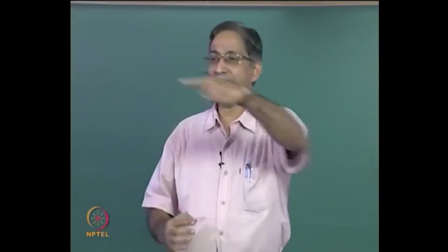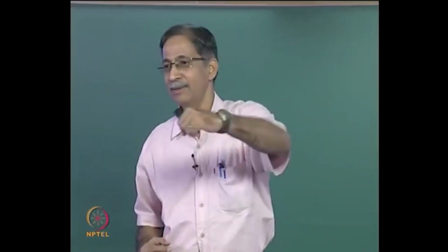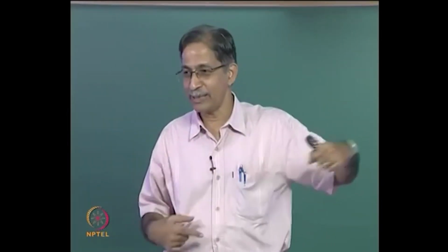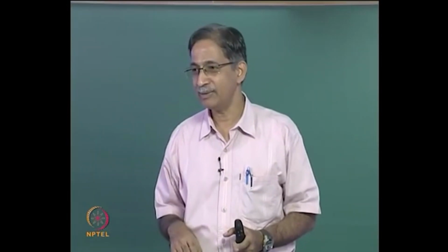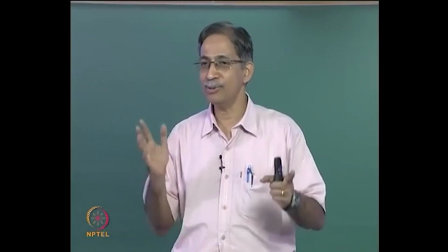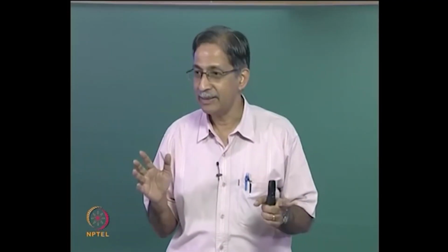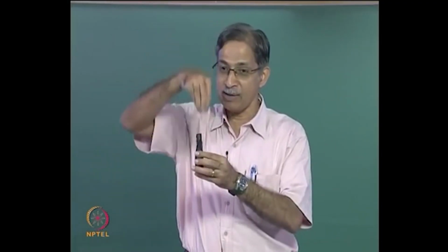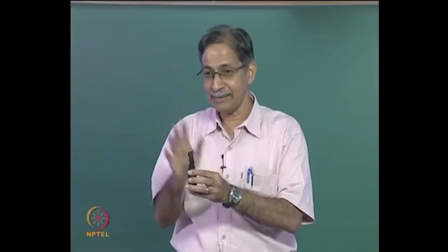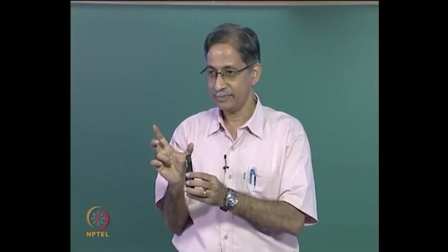They are slender, and so they are going to be vulnerable. Let's say there's an impact. Let's say a ship comes in. You have ways of reducing the impact. Then these columns are subject to lateral loads. Then you'll surely get P delta moments. So as an engineer, you should know how to calculate P delta moments, right? That's where all this knowledge comes into play. Now if you had a heavy load acting, then that delta is going to be large, and so you have to calculate correctly.